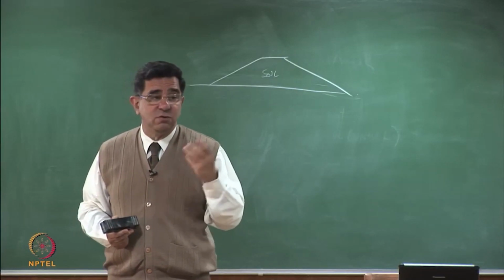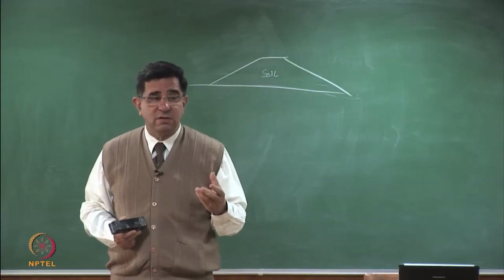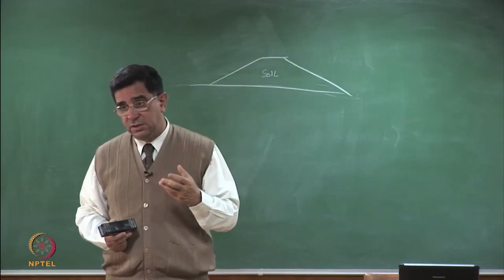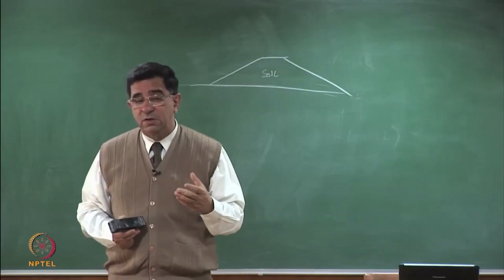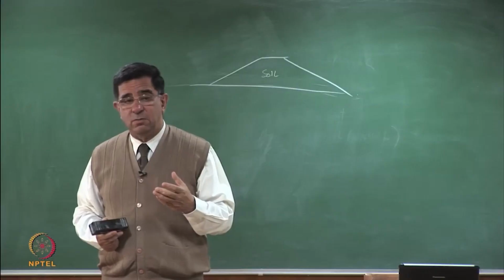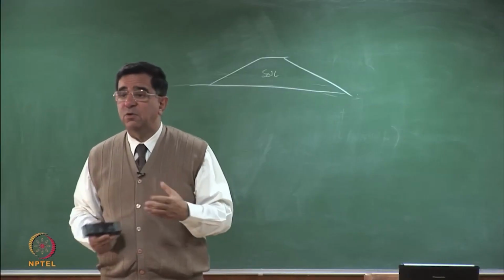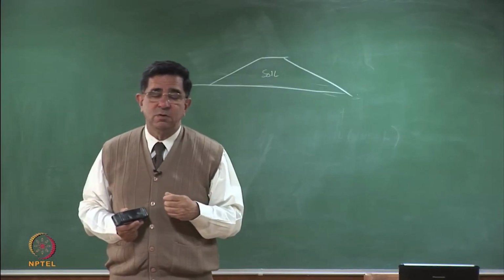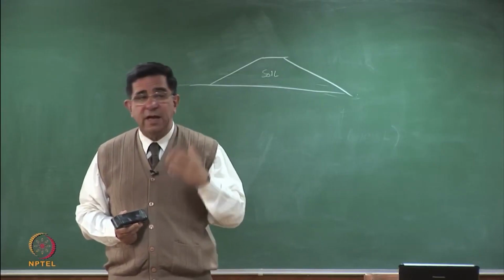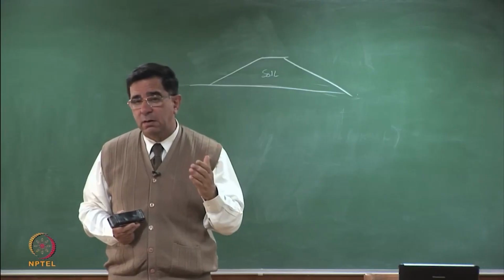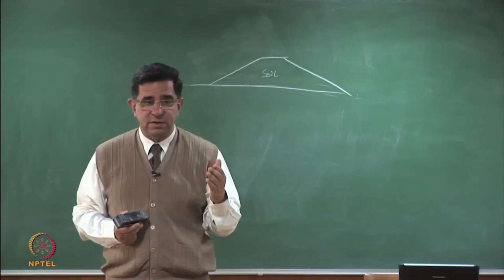If it is gravel, you will have to use large size triaxial equipment, or you could use the direct shear test. In the direct shear test also, the conventional 6 centimeters by 6 centimeters direct shear box cannot be used for gravel. You will need a bigger direct shear box. So I can do the tests in the laboratory. Triaxial tests give better and more accurate values than direct shear tests.